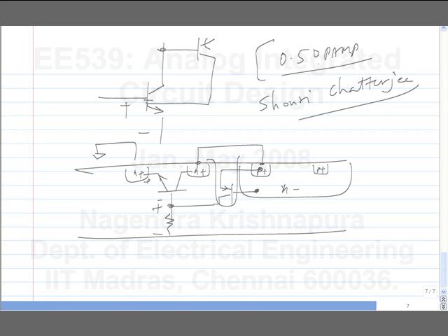But the thing is, one of the things that would drive people to make something like this is that when you scale the technology and go to lower power supply, the advantages for digital are very obvious. First of all, you scale the technology so circuits become smaller, and also you shrink the voltage. The power dissipation, which is dependent on the square of the voltage, and also the capacitance will go down, okay, proportionately to the scaling of the power supply. Whereas for analog, it's not very obvious.